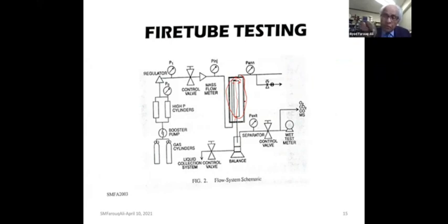So a combustion tube test essentially means that you take the oil, the sand and the water in the right proportion, fill the tube, then ignite the tube on the top and inject air on the top, and the combustion zone will move. As it moves, collect all the gases, liquids, everything. This is all the equipment to do that, and analyze the gas for oxygen, CO2, CO, nitrogen, any hydrocarbons, any sulfur dioxide, any H2S, and then derive the parameters.